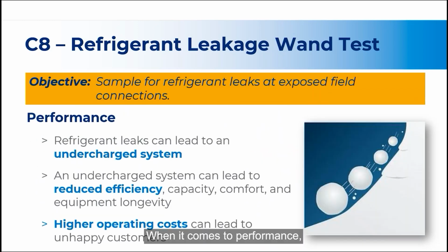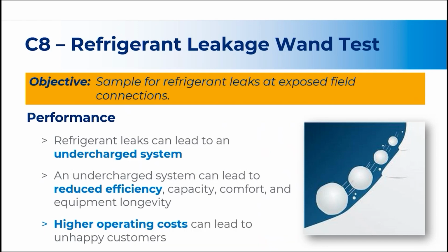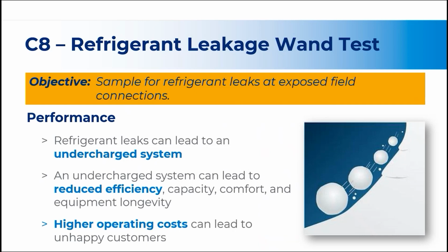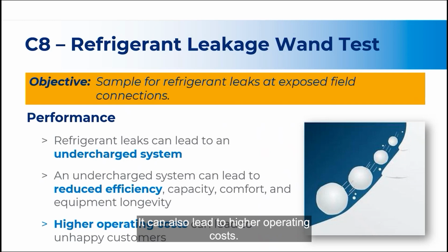When it comes to performance, refrigerant leaks can lead to an undercharged system. The more substantial the leaks, the greater their impact on energy and operational performance. An undercharged system can lead to reduced efficiency, capacity, comfort, and longevity of the equipment. It can also lead to higher operating costs.